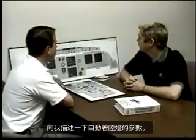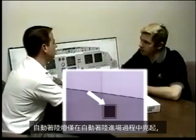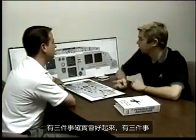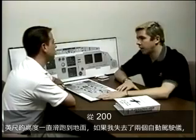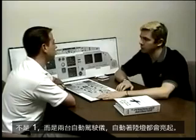Describe to me the parameters in which you get an auto land light. Okay, auto land light only occurs during an auto land approach, and it's armed at 200 feet. There are three things that are going to illuminate the auto land light. From 200 feet all the way to the ground and rollout, if I lose both autopilots, not one, but both autopilots, the auto land light's going to come on.